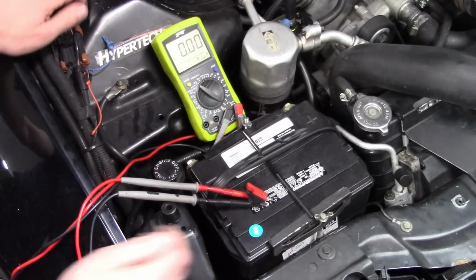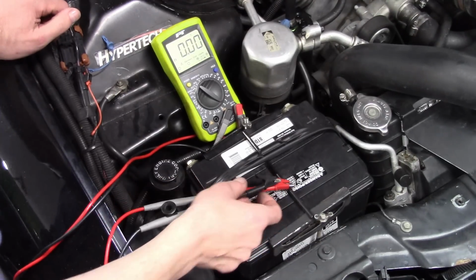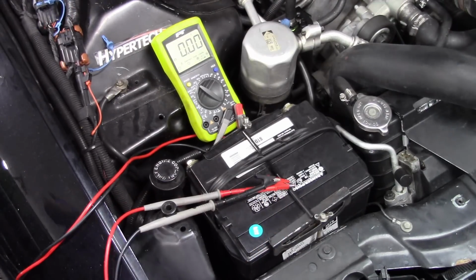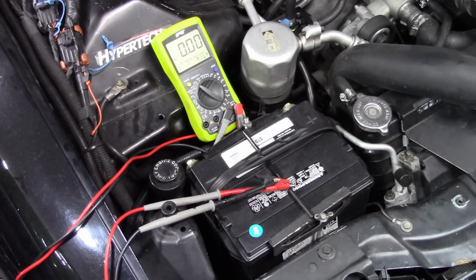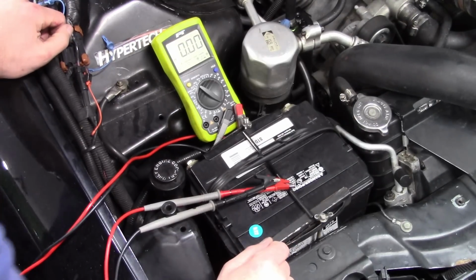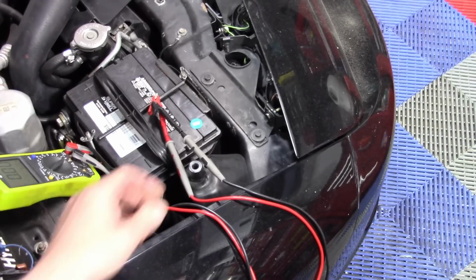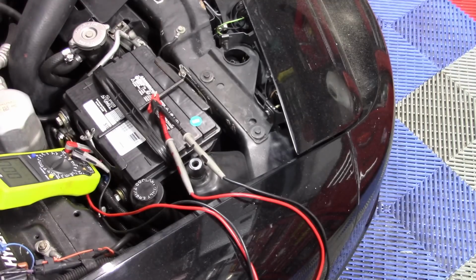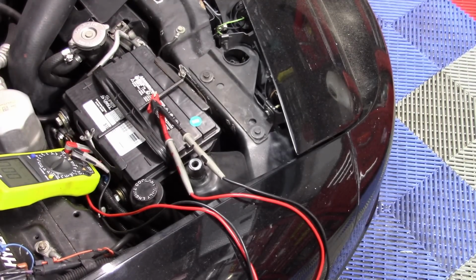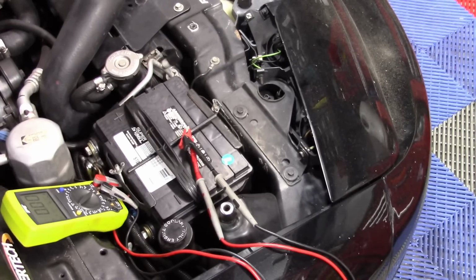Okay, the next thing it wants us to do is to measure a voltage drop. In order to measure a voltage drop, the first thing we know is we have to have current. We need to turn something on. The first thing that comes to mind for me is probably a headlight. If I look here, we've got a 2-wire headlight connection right here. The only thing is this car has pop-up headlights, so I may not be able to access it if we pop the headlight open. I think there's a way I can turn the lights on, though, without popping the headlights. So let me give that a try.